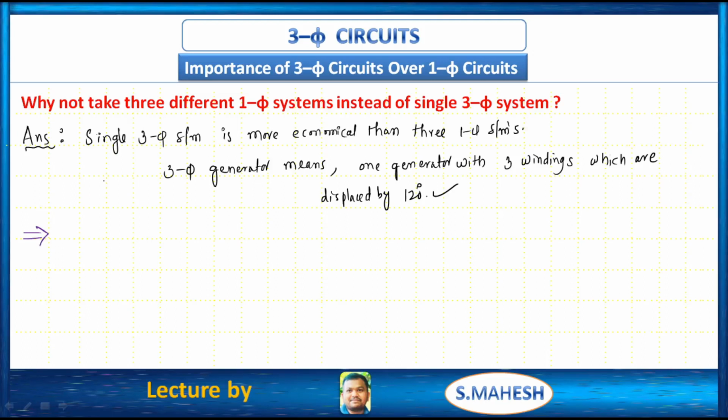in a 3-phase generator there is only one rotor and hence one speed and a common frequency for 3 phases, right. Only one rotor. If we consider a 3-phase alternator, we have one rotor and one stationary part, the conductors, which are displaced by 120 degrees apart and are stationary, but the field is a rotating permanent magnet. The field is rotating and the outer part is stationary.